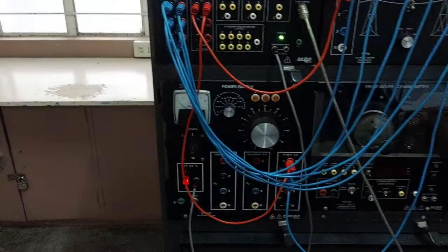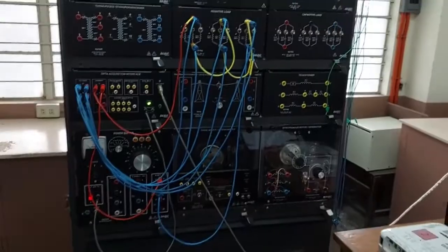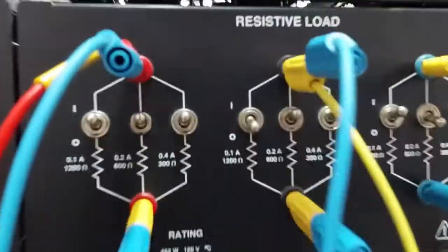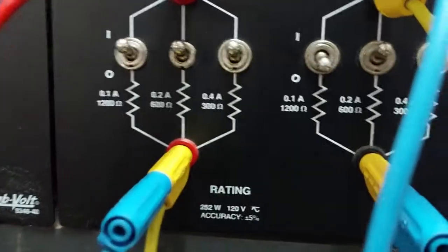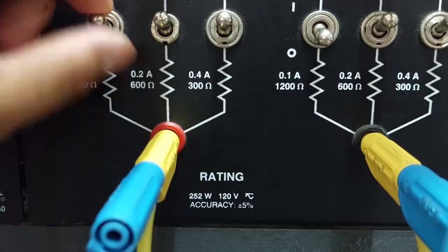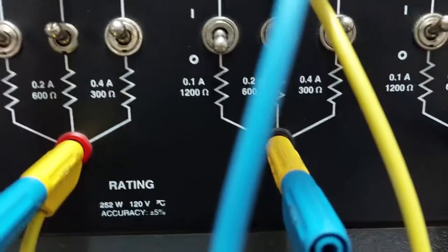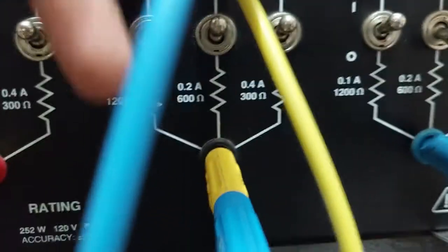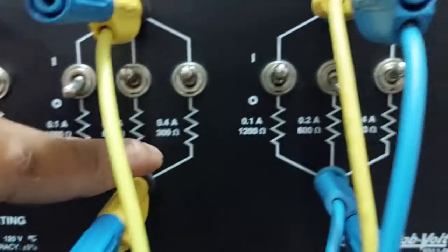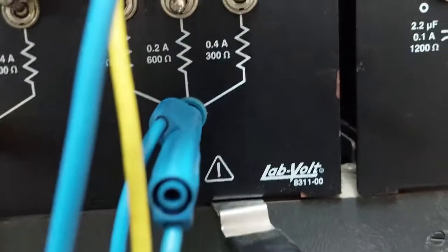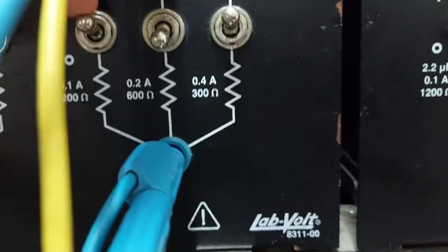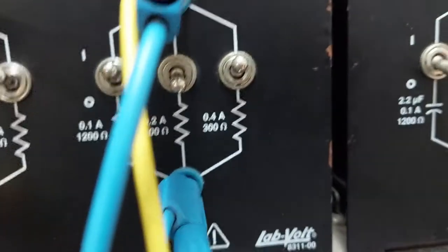So that is our connect. Okay, so ito yung kinonnect natin kanina, right? So first, I would like to show you the load. The load is 171 ohms because it is the parallel combination of your 1, 2, 600 and 300. And then next is 200 ohms because it is the combination of our 600 and 300. And next is our 240 ohms because it is the combination of our 1, 2 and our 300, right?